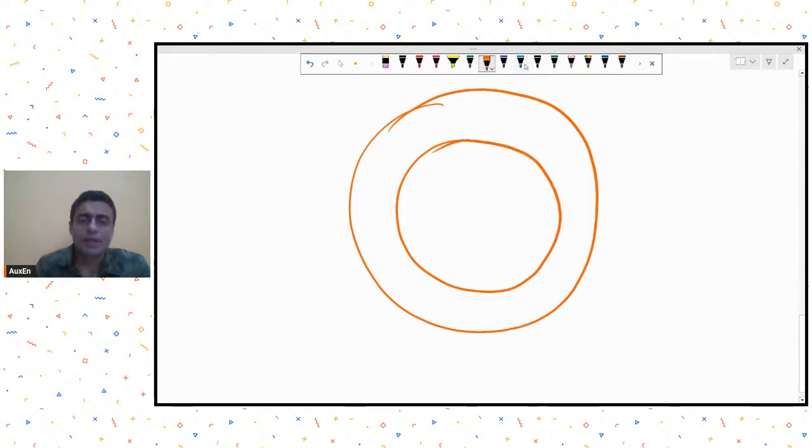In plan it will be a ring raft like this, and maybe now this annular raft you may have to give for columns which are placed like this on the periphery. Okay, so suppose you have some structure which has columns like this, peripheral columns. For this you may have to give annular rafts.